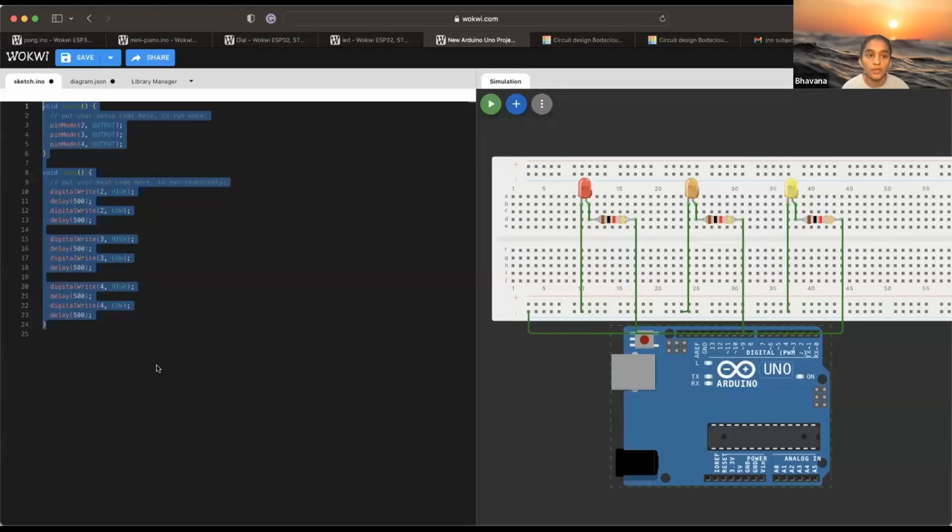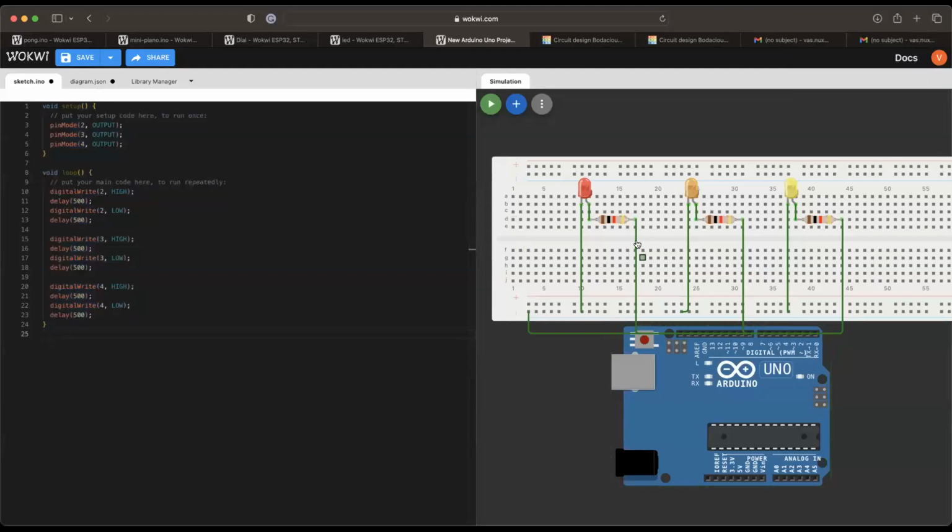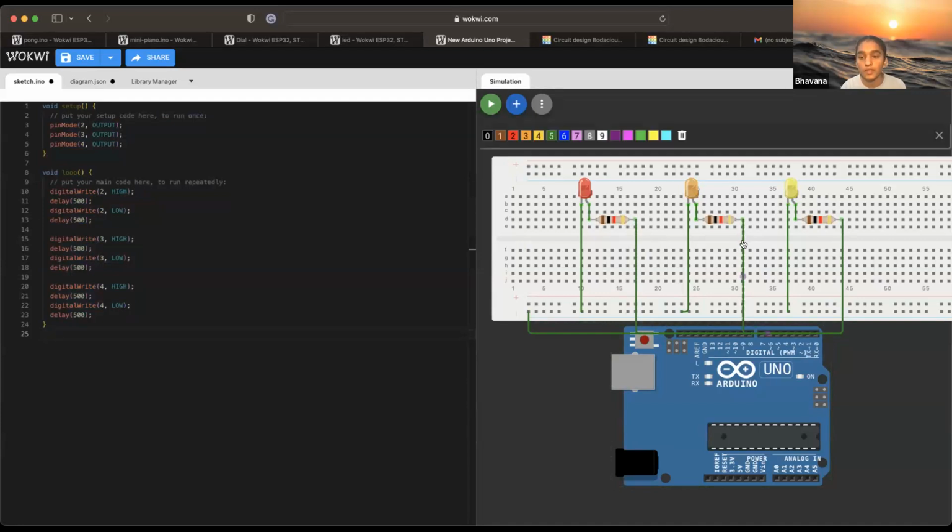Okay. Share. So you can see my screen, right? Yes. So these wires, the ones that are vertical to the right of each of the resistors, delete all of those 3 wires. You just hover over them, select them, and then delete. Okay. And then you have to connect them to pin 2, 3, and 4. Your connections are wrong. That's why the LED didn't light up.